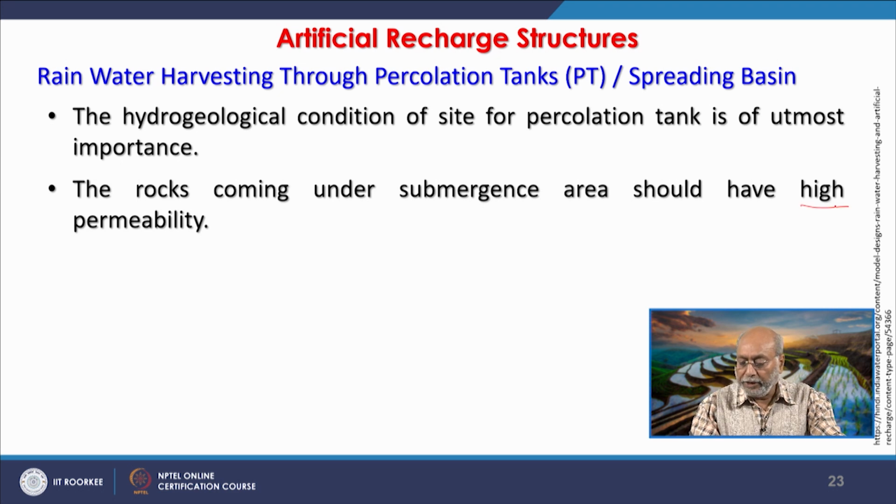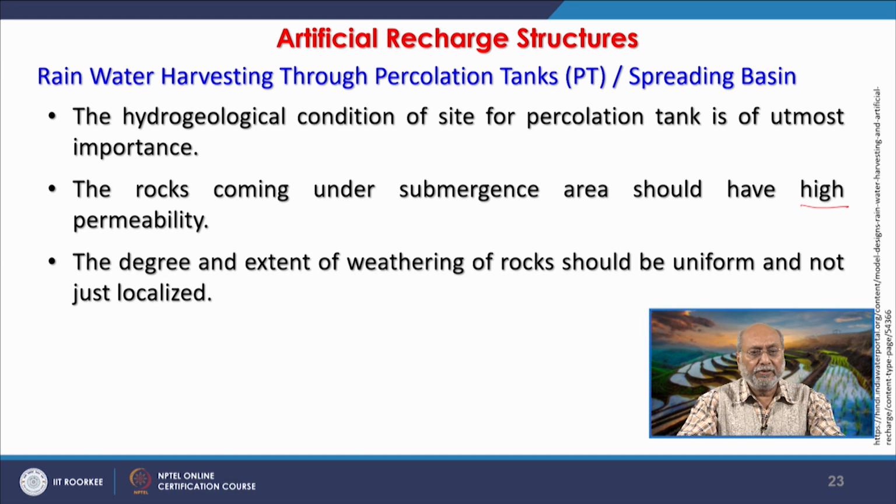I would like to say here that all the time one may not have highly permeable rocks at the surface. So even if there is permeability only to some extent, it does not matter; such tanks can still be constructed. The efficacy may not be that great, but whatever water is being wasted will be stored for some time and definitely it will recharge the groundwater regime to some extent. So there is no harm if the construction cost is not much.